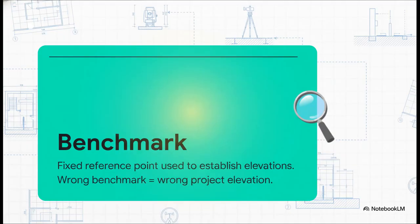Before a single shovel even scratches the dirt, we have to establish the fundamental lines and fixed reference points that are going to dictate the entire geometry of the project. And for that, we need a benchmark. By definition, your benchmark is the absolute starting point. It's a fixed reference used to establish literally everything: finished floor, drainage, and grading elevations.